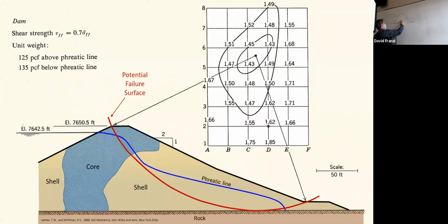then you're really in trouble, because now you've got a high hydraulic gradient coming out, and you can get spring sapping or piping. Piping and spring sapping are two very analogous processes. Spring sapping is where natural groundwater comes out, and it removes some soil particles, and everything kind of collapses simultaneously into that area that was vacated.